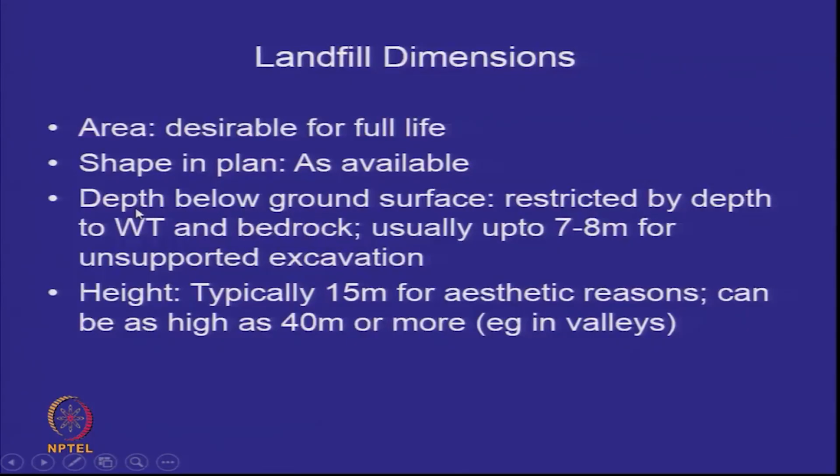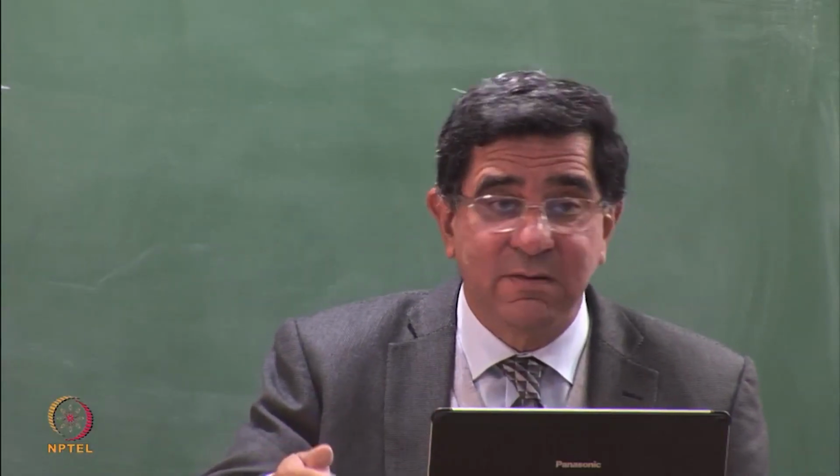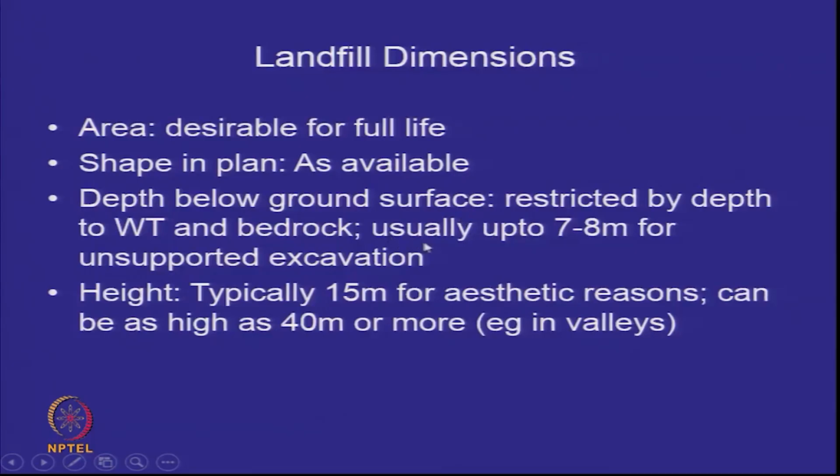How deep can you go? When we are trying to actually say that the municipality says don't go beyond 15 meters. Well, then can I go below? Sure. How deep can I go? Well, somewhere there will be a water table, somewhere there will be a bedrock. If neither of the two are available, how deep will you go? Well, we never typically go deeper than the unsupported excavation we can do in that area. So usually we go 7 to 8 meters for unsupported excavation. Technically we can go to very deep areas as well.